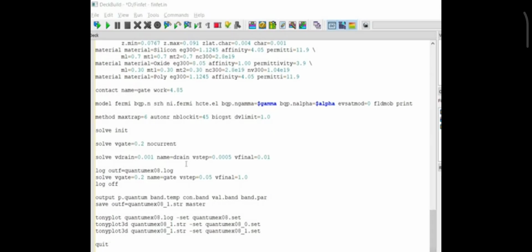This example describes the modeling of a FinFET device using BQP and energy balance in 3D. The quantization inside the channel is almost two-dimensional. The 3D device structure is created in DevEdit 3D and the required models are set.